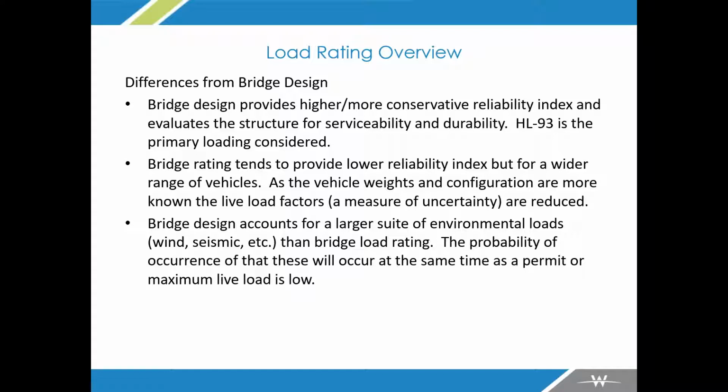And that's really why, when you look at legal vehicles, or in particular the overload specific posting vehicles, if they're running a very specific overload where you know the exact axle configuration and your weight to a pretty high degree of accuracy, then that live load factor could come down a bit from the 1.75 to more of the 1.3, 1.35 range, which is what code allows you to do, because that's more well known.